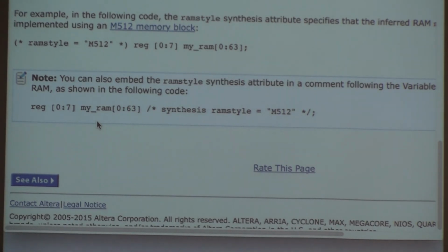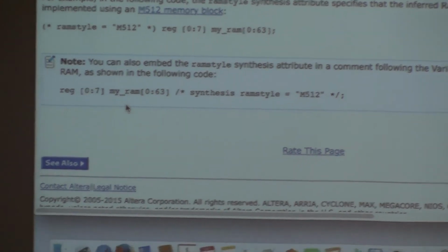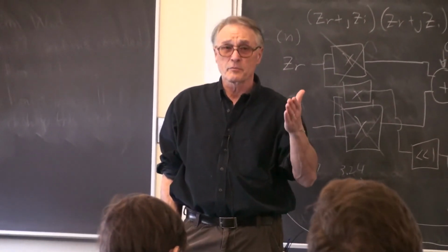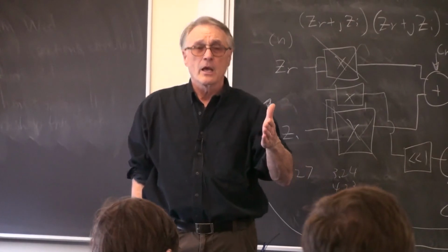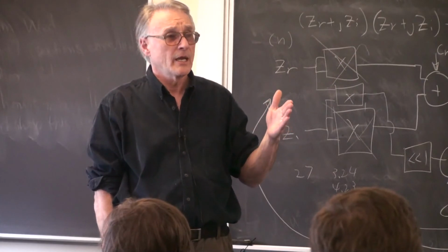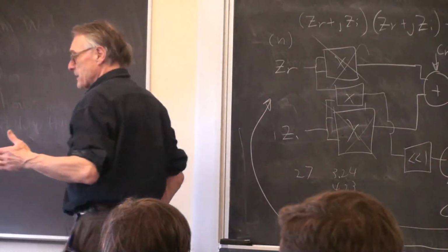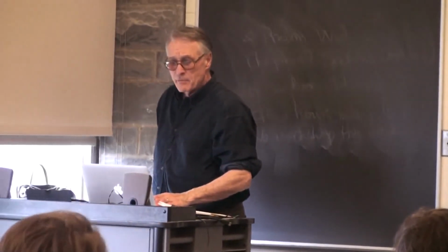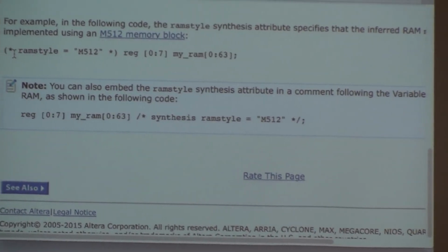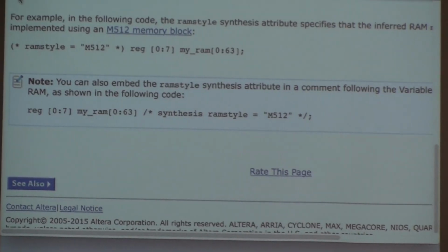To get the timing right for M10K blocks, I believe that you have to, in your Verilog, insert pipeline registers in the input. That's true, yes. You have to insert pipeline registers in the input and use the templates given in the HDL style guide. Has anybody tried this style of comment? I don't know what a parentheses star does. Is that also a comment? I don't recognize that syntax.